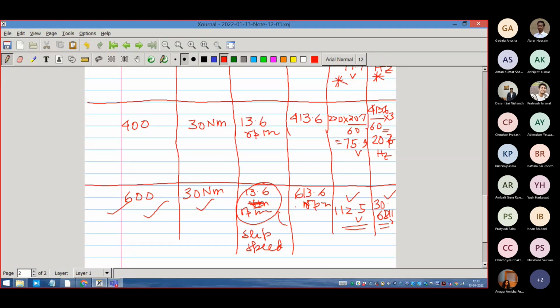But suppose the temperature of the machine has increased, the resistance has slightly varied. Then in our case, we will not be able to arrive at the correct amount of torque, because we have assumed the resistance to be constant. But in the closed loop method, it is already included, because it is directly working on the speed error.